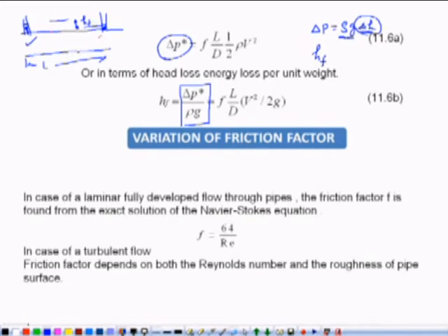Here pressure is more, here pressure is less. So this loss of pressure is in terms of the head loss. If we put a piezometric tube here at a distance L in a pipe, then even if we have a horizontal pipe, the water rises up to a certain height, and the difference in height in these two piezometric tubes will be HF, right. This is the meaning of head loss between these 2 points.